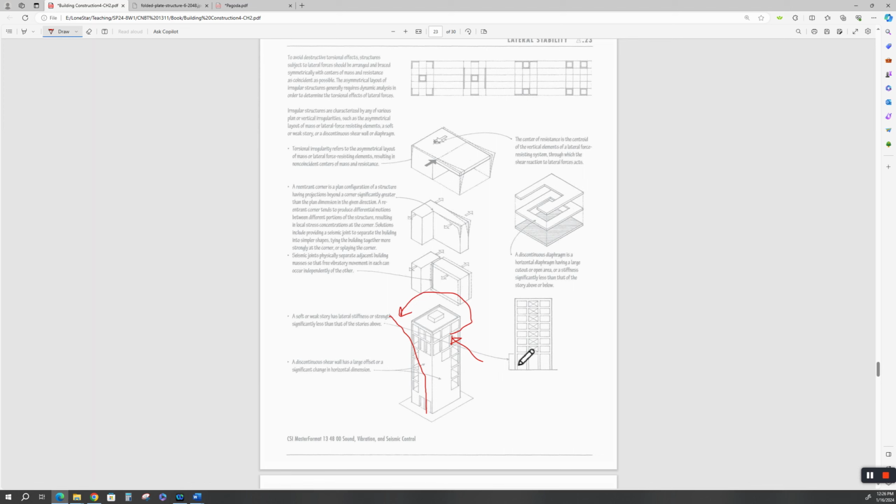Torsional stresses around the center if the wind loading is of a certain direction. Let's say the wind's coming from this direction, off that corner. It's going to produce stresses going in this direction, and it'll produce stress going in that direction. And what's that resultant thing? Come in that direction. So that resultant is going to want to put a little twist to that building.